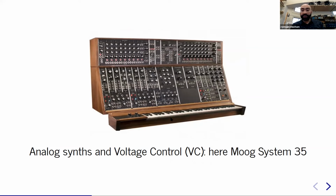And basically the rule that was used for that is that 1 volt was equal to 1 octave, okay, for this type of keyboard. So when you press a key, you just create a DC voltage, and this DC voltage corresponds to a note or a frequency on the keyboard, okay? So that was their standard. Very basic standard, right? It's just DC voltage, and a specific voltage corresponds to a note.